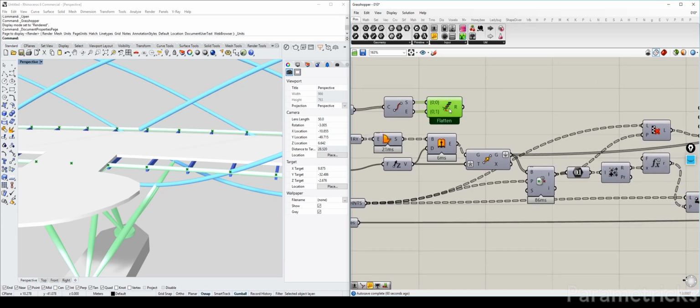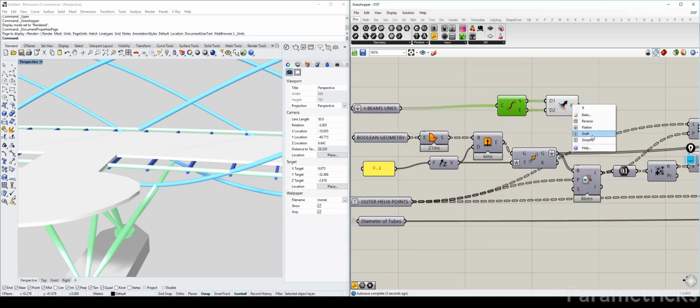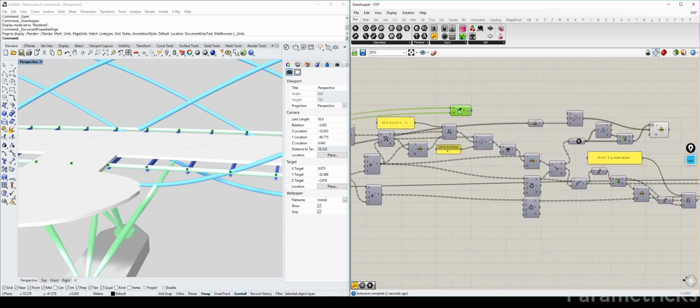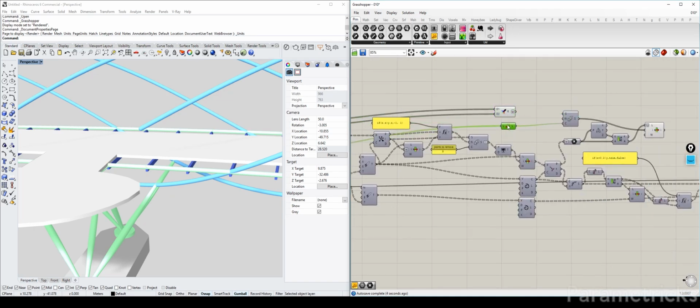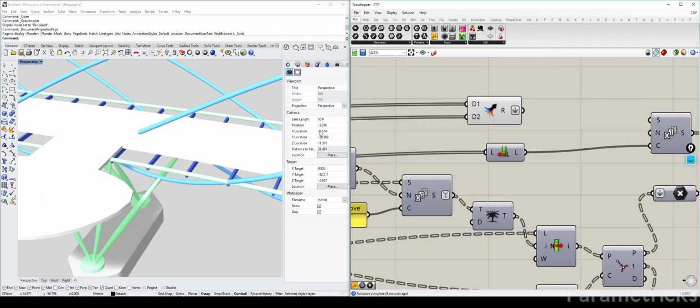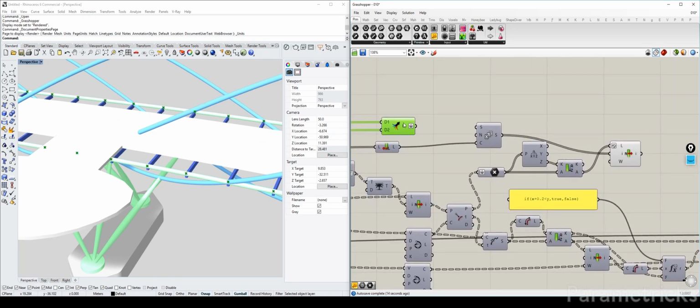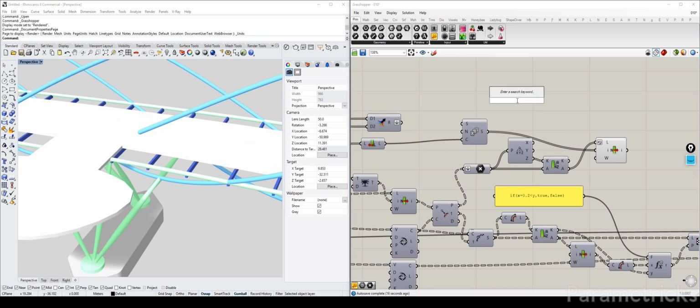Yeah, so let's copy that and Control Shift V to paste that. Let me see. This one has an entwine. Do I need an entwine? Doesn't really matter. Well, we can keep the entwine actually. It's the same thing, because in the end, what we're going to do is flatten the whole list, because we don't know which point it needs, right? I mean, who's to say that point number 1 isn't on the side that we want or on the other side? So it really doesn't matter whether you use a merge or entwine, because we'll be flattening that anyway.